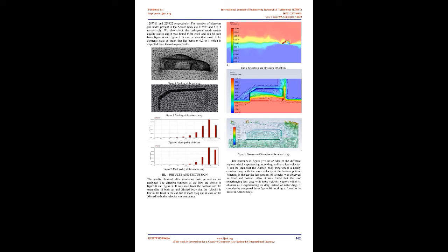The models of the vehicle were designed in SolidWorks and then imported into Ansys Fluent 2019R3. An enclosure containing the vehicle model was made to define the finite volume in which the simulation was carried out. The Boolean operation was performed in which the vehicle body was subtracted from the fluid domain. Meshing was done for the complete system, which comprised triangular as well as tetrahedral mesh. After meshing, named selections were given to the different walls and to the vehicle enclosed inside the enclosure.